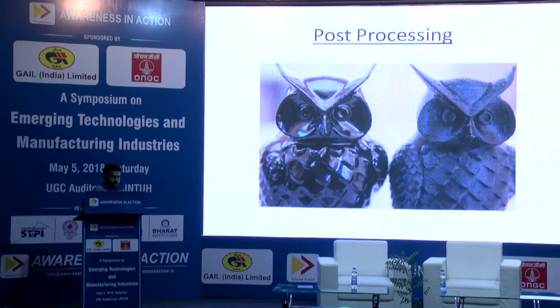For this particular part, which is about 6 centimeters in height, you keep it for 2 to 3 minutes and the vapors basically eliminate the lines. You have to be very careful: if I leave it more than 5 minutes, it will just vaporize, so I should check the time and monitor it continuously within 4 minutes. Since it is created layer by layer, that is a 300 micron line that I am seeing over there. It doesn't look good, right? So the vapors eliminate those lines and finally you get a glossy finish like this.